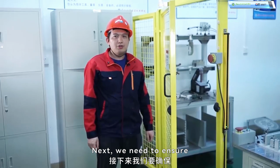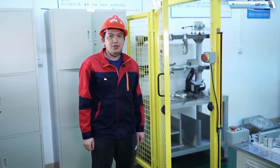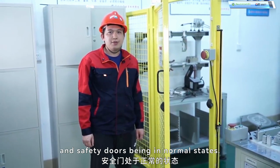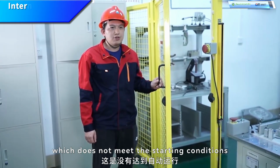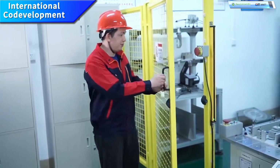Next, we need to ensure that the entire robot system's safety systems are in normal condition, including various emergency stop switches, safety protective light curtains, and safety doors being in normal states. As we see now, the safety door is not closed, which does not meet the starting conditions for automatic operation. We need to close the door.